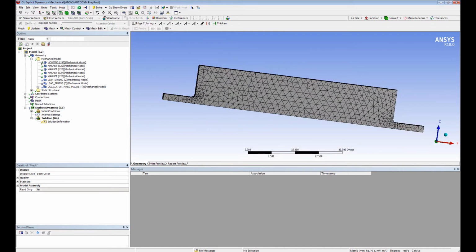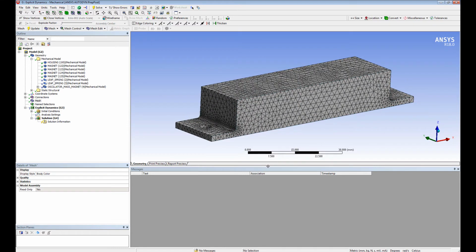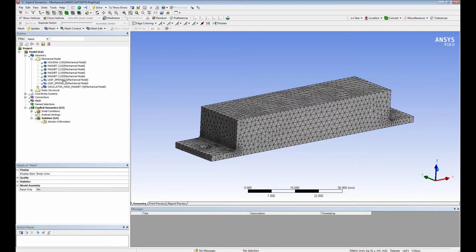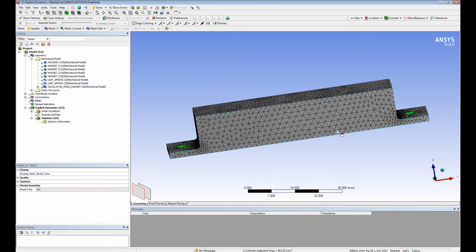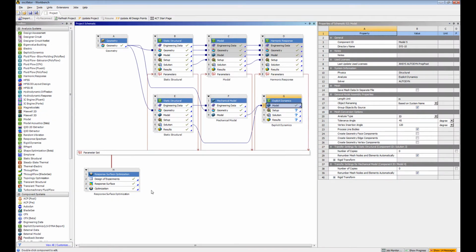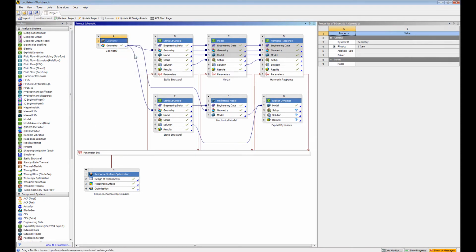Now we need to drop this against something. So it's typical in electronics drop testing to model a 1500G half sine shock spectrum. And we can put that through the mounting holes here. So we'll create yet a third piece and create a large mass based on that. So I'm going to duplicate this geometry